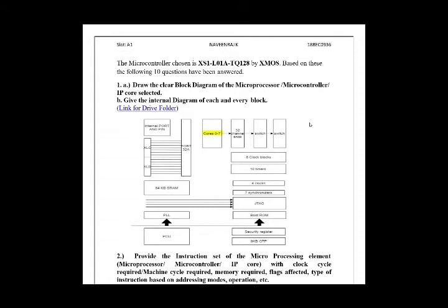The ports and the links seen in the above section, the XConnect links which run across the cores, channel ends and switches, are multiplexed, allowing the pins to be configured for use by ports of different widths or links.